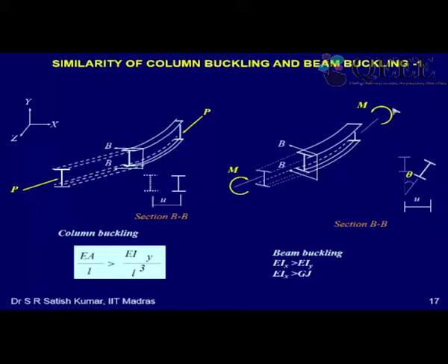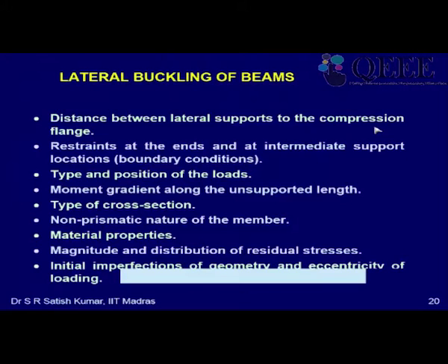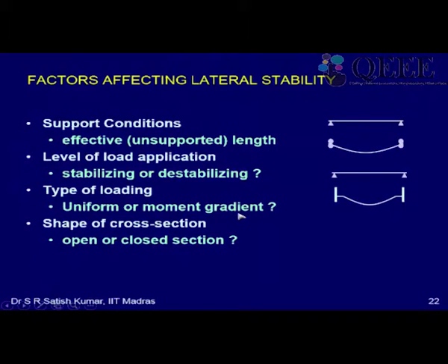And anyway, the ends are not laterally buckling, so even if the moment is 0 there, it's not going to matter. But the M max will be only at one cross section in the middle. When M max reaches this MCR for this case, the beam may not really buckle, or it might not appreciably buckle, I should say. Critical buckling strength will be slightly different. So now the question is how to consider the moment gradient. We'll come back to that later on in the subsequent slides. So that also matters. Okay.